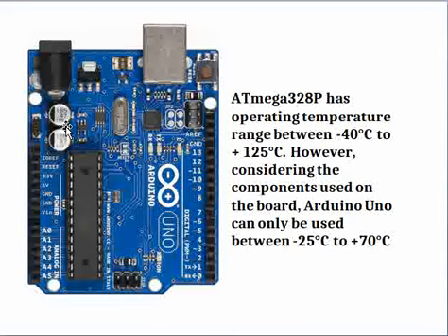It's a commercial application where people use this board as a hobby project, and develop a number of applications around it, and ultimately this is targeted to improve the code building capacities, especially among the students. And slowly it gained popularity and it came to industrial applications as well. But considering the temperature range, you know now that Arduino Uno is a no-go if your operating temperature ranges are higher.